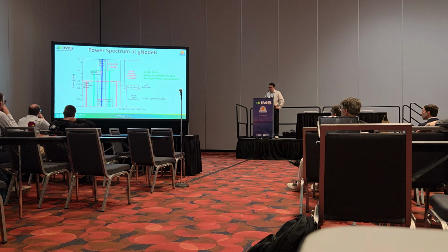So we need to reduce this self-interference to the noise floor level, and this transmit power, due to the PA nonlinearity, we're going to have ACLR around 30 dB lower, like the green line, and there will also be transmitter noise around here. For sub-band full duplex case, we need to reduce this power to the noise floor compared to in-band full duplex from here to the noise floor.